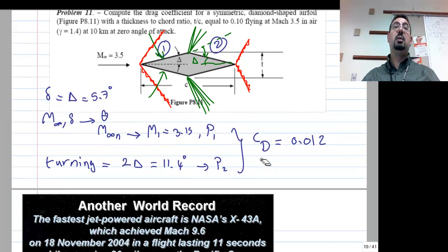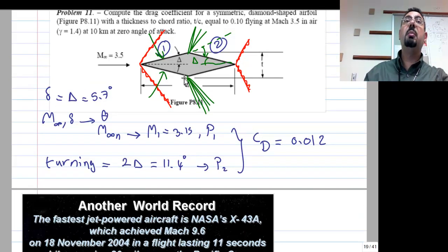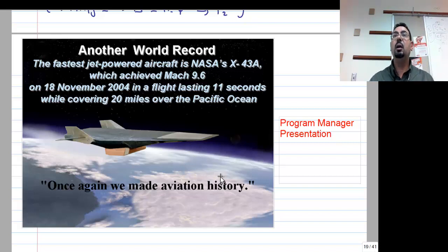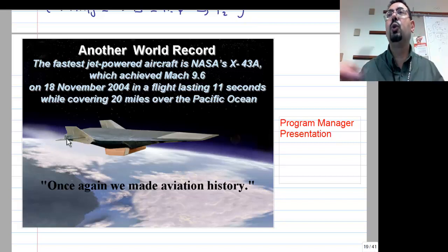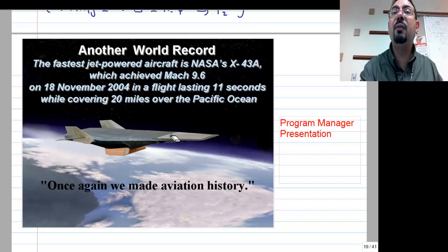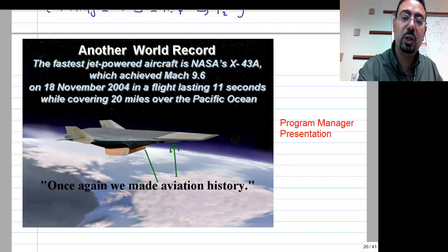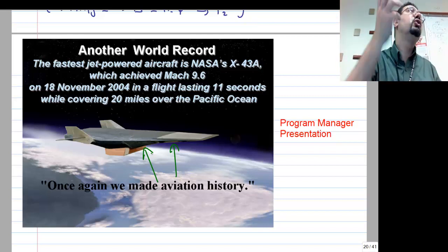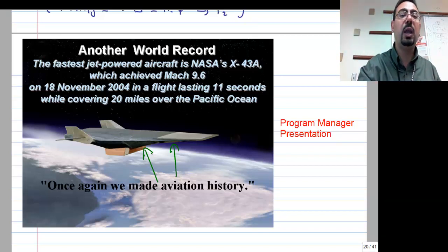So that they can use the same idea to actually make those things fly. So those hypersonic vehicles, they are basically carried on the shock wave they are basically generating, right? The lift, there is no wings. Those are not really wings. Those are kind of control surfaces, right? But the lift is generated by the pressure here, right? You can imagine there's pressure here and there's pressure there, right? And it's this pressure, the vertical component of it, that's generating the lift force